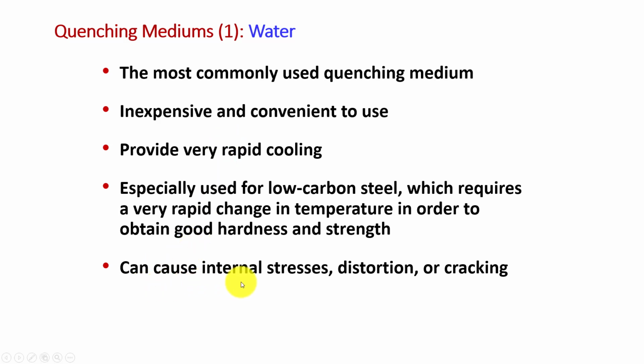Now the problem is, it can cause internal stresses, distortion, and cracking. This is big. Not all steels can I take and quench in water. Some steels, you do that, it will quench crack. And we're going to talk about that in some later slides here.